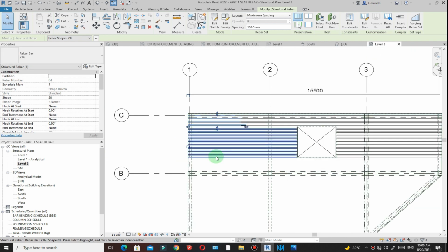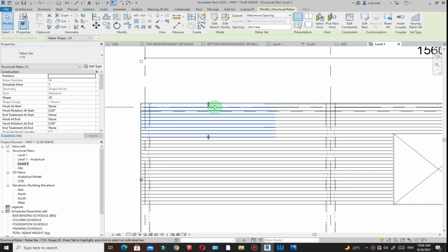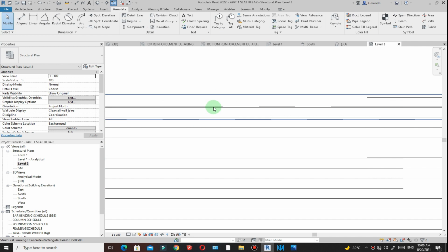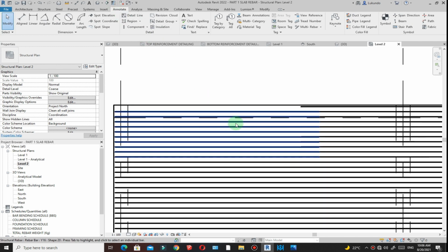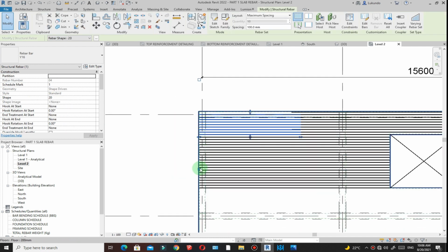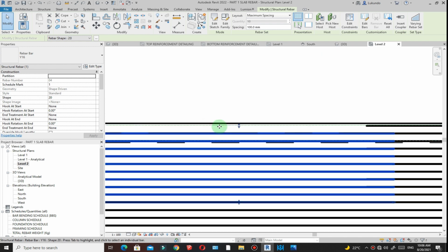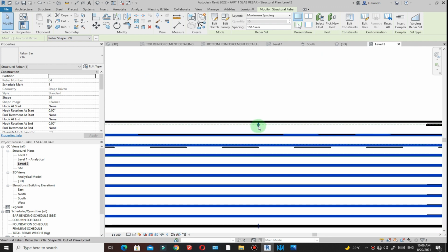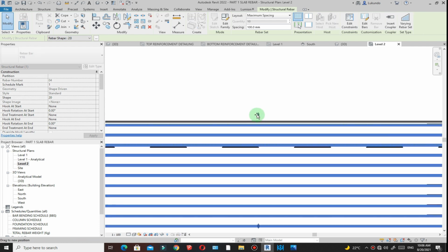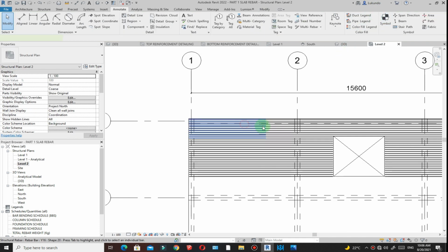But this time we don't want to remove the last rebar, so make sure that you activate it. Okay, so select on the rebar, make it thick lines, select on the rebar once again, then it's like I don't have the last rebar. Where is it? Okay, as you can see, I'm able to drag it and snap there. If you want, make sure that you constrain it there.